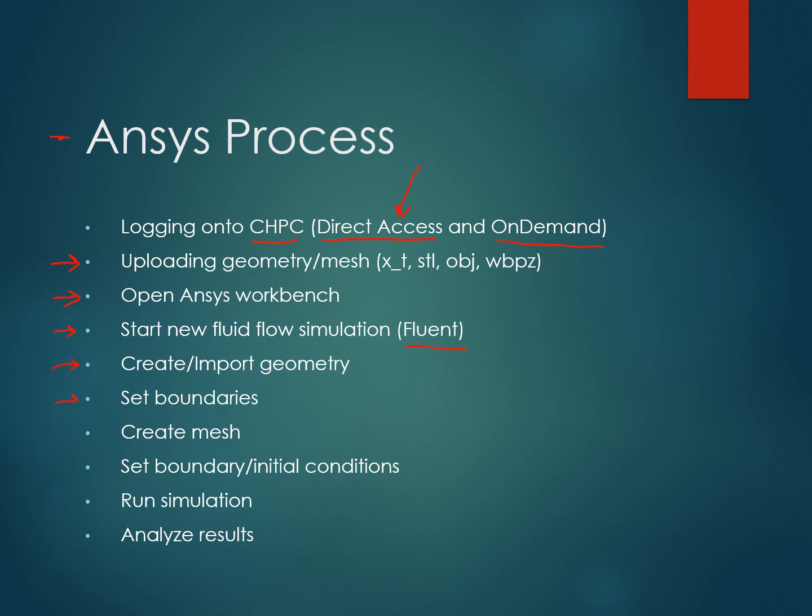We'll have to set up our boundaries when we create this mesh. So our first simulation here will be a simple 2-dimensional fluid flow, where we've got the bottom set up as a wall, and we'll have fluid flowing in at a very uniform rate. And so in terms of creating these boundary and initial conditions, we need to set up a velocity for the inlet flow. We'll need to set up this as a wall. And then this is going to be our outlet.